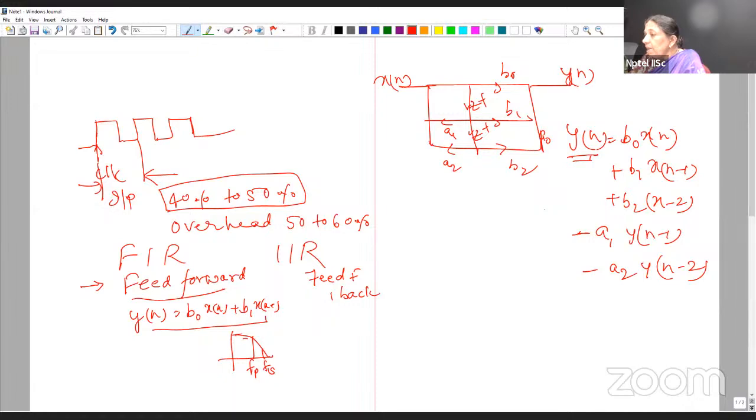Only the disadvantage in parallel section is, because in the DSP processor, we assume the number system, addition can have an overflow, whereas the multiplication is not going to cause any overflow because we are considering fixed point implementation. That is the reason why even for IIR filters, we go with the cascade section.